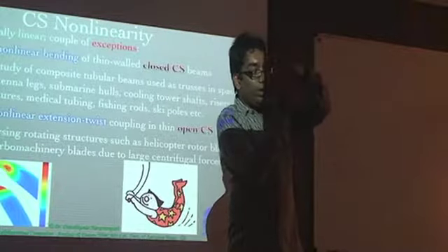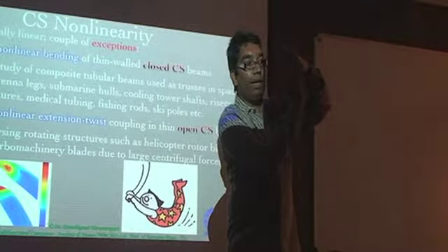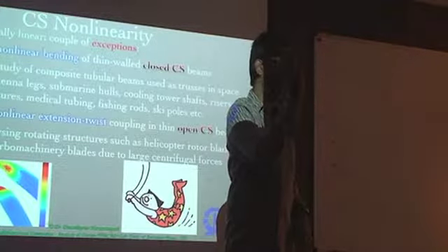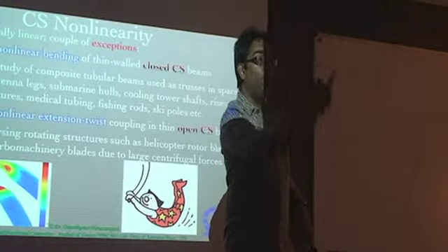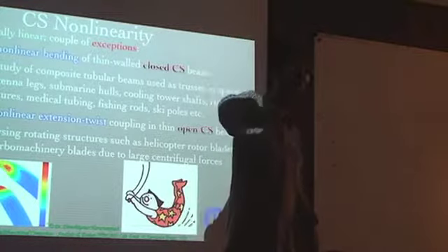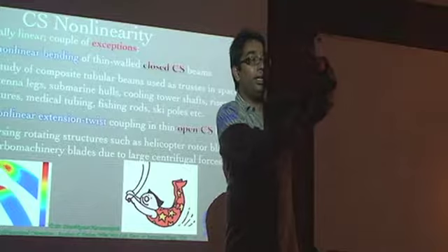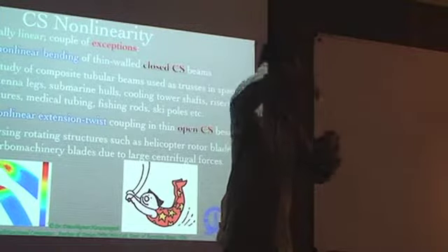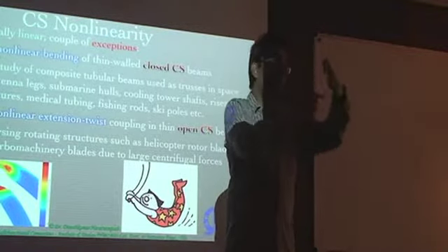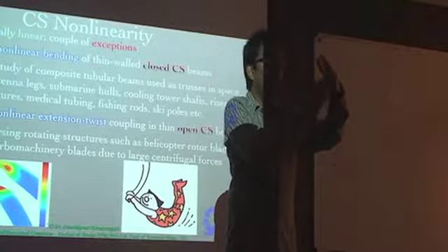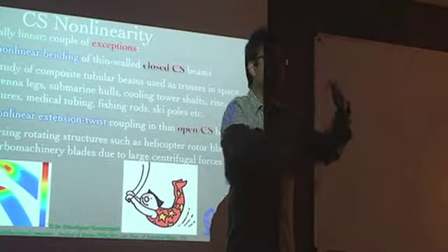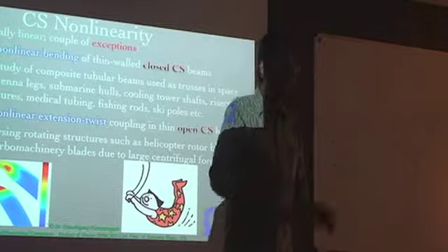load. So around that location you can take a small area, and for that location you can do a 3D analysis giving the boundary conditions from the results of your 1D analysis, beam analysis, and then of course after recovering the 3D results, you can apply that as the boundary conditions, and then you can get the exact stress distributions and or deformation patterns in that location.